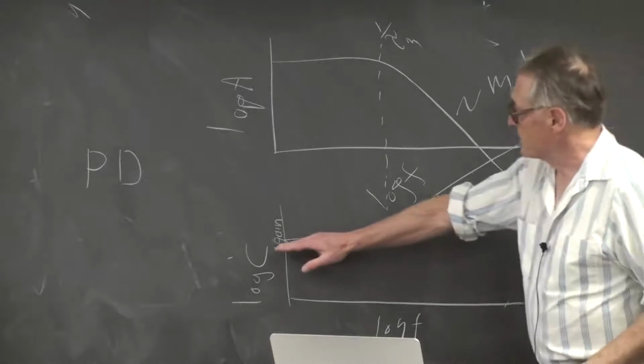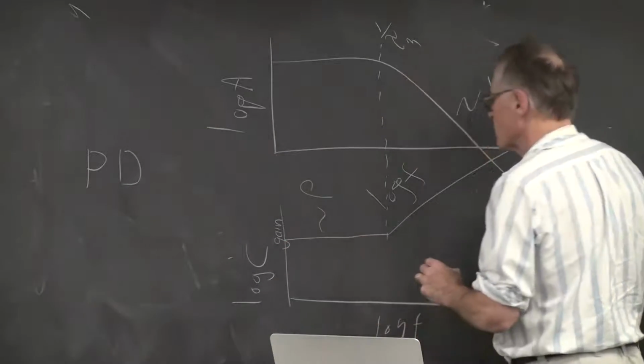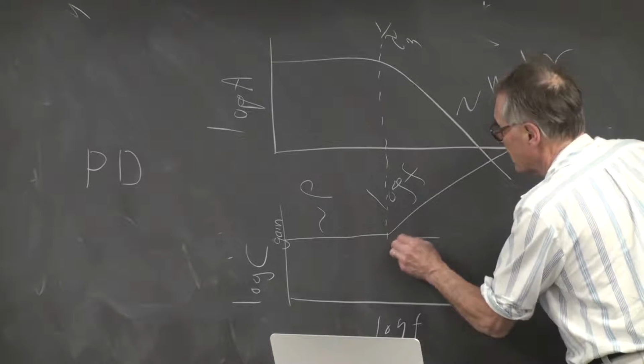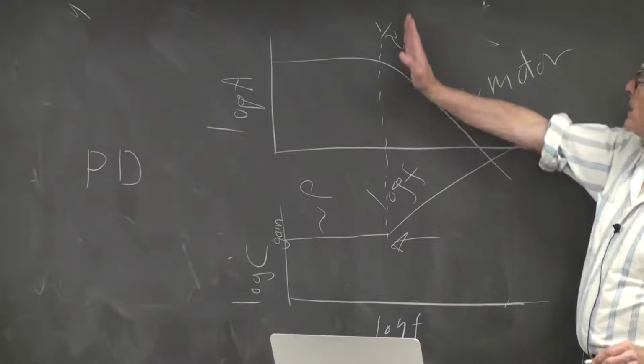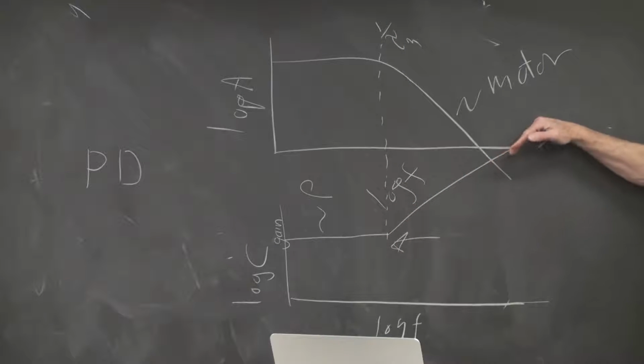So we have a gain of the system down here. This is the proportional term, and then the differential term is going to be set by the ratio of P over D, which is going to say when does the differential term become dominant and keep the phase shift bounded at -90 degrees.